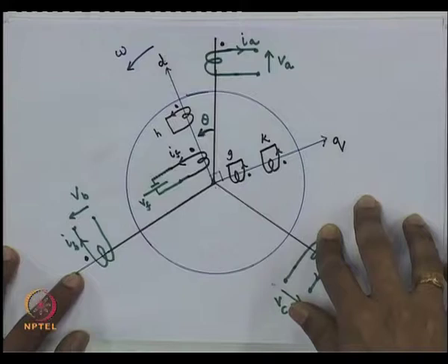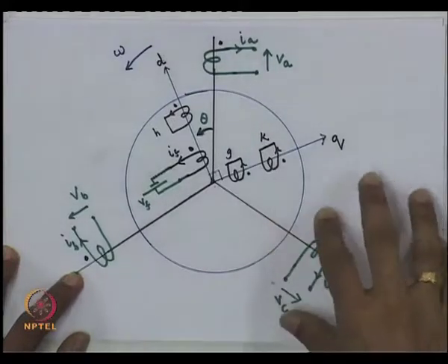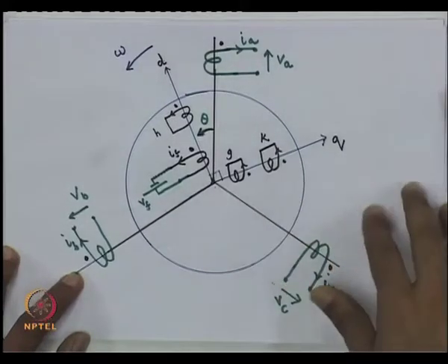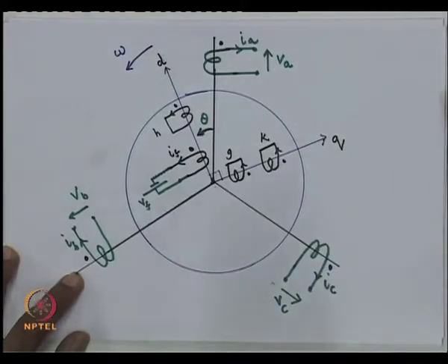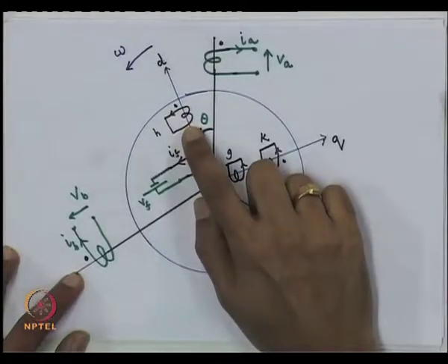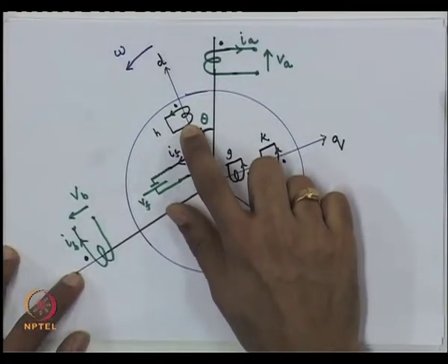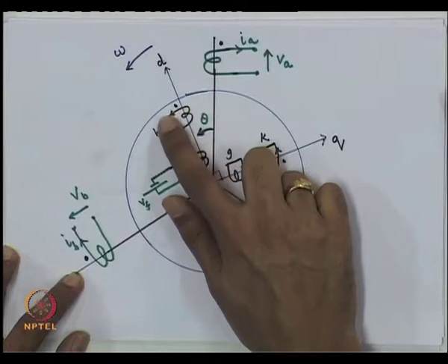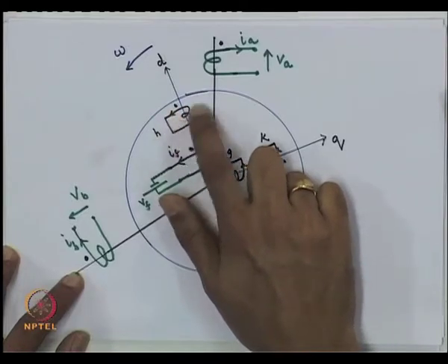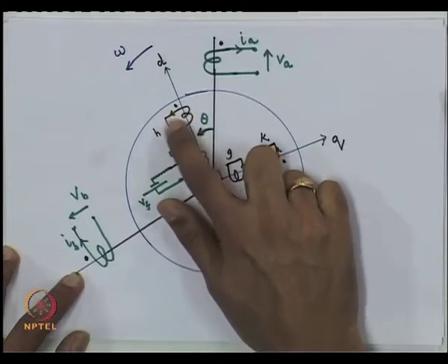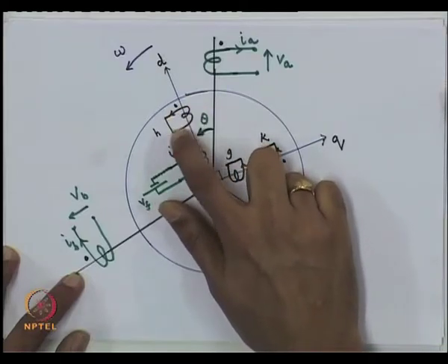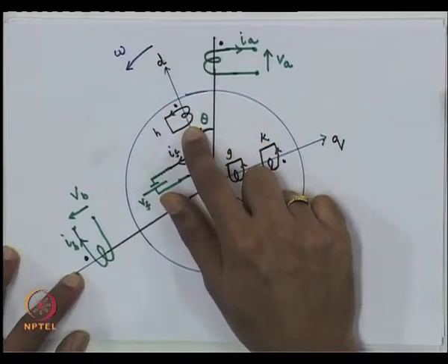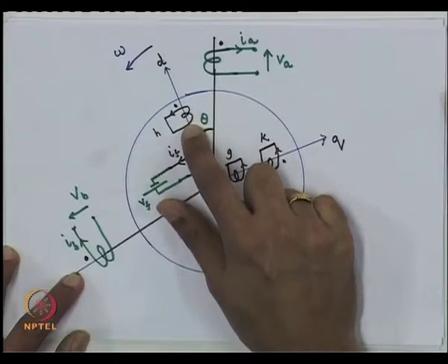So, what you really see is the effect of the eddy currents, or what are known as the squirrel cage currents or the damper currents, as these are all alternative names. The effect of this is captured using coils which are short circuited on themselves. After all, a damper winding or eddy currents are a kind of circulating current. So, a basic damper winding is represented by a coil of this kind. Of course, this is an approximate representation.